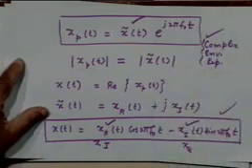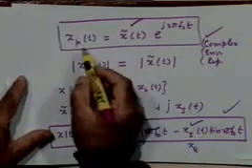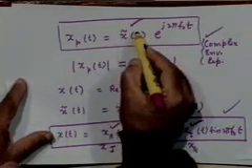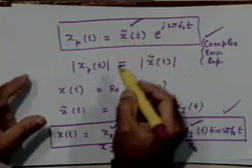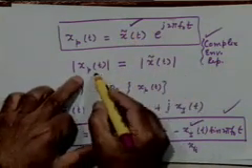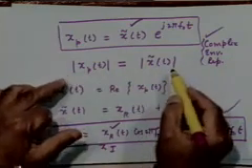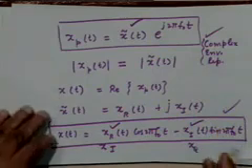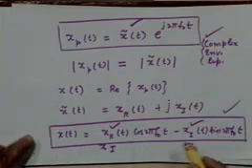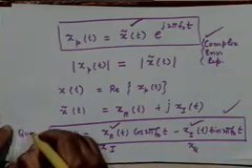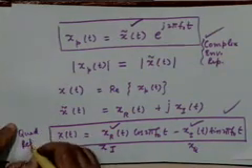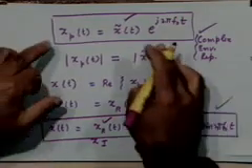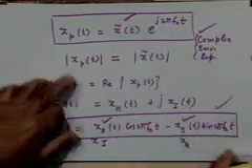So if I talk about a complex envelope representation, it is this, where x tilde t is called the complex envelope. Now we have seen that the real envelopes, both of them are the same, right? And this is called the quadrature representation. So both these representations have names. This one is called the quadrature representation. This is called the complex envelope representation.